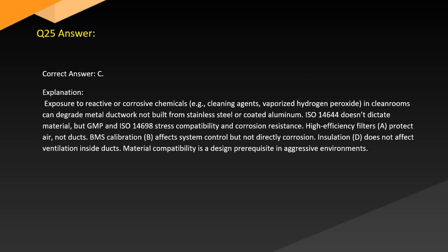Answer. Correct answer: C. Explanation. Exposure to reactive or corrosive chemicals, e.g. cleaning agents. Vaporized hydrogen peroxide in cleanrooms can degrade metal ductwork not built from stainless steel or coated aluminum. ISO 14644 doesn't dictate material, but GMP and ISO 14698 stress compatibility and corrosion resistance.